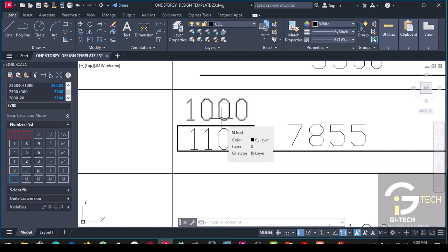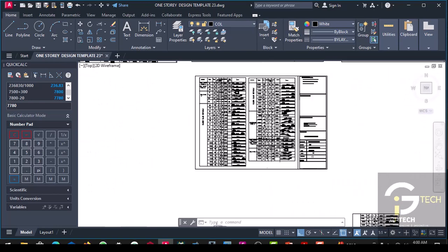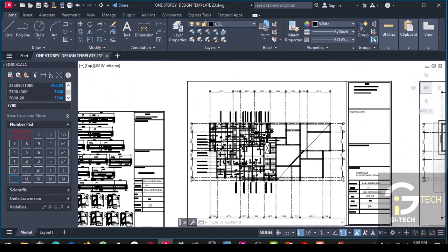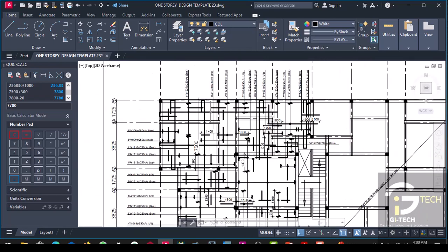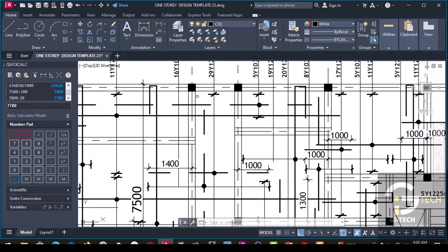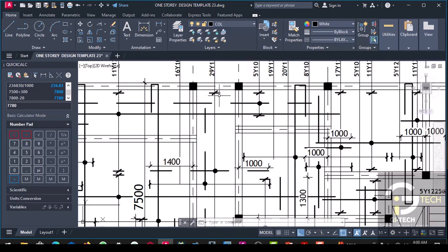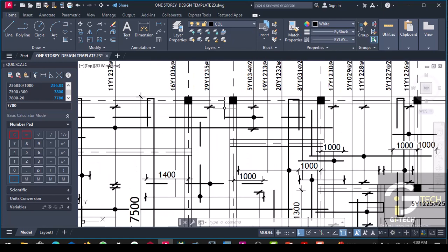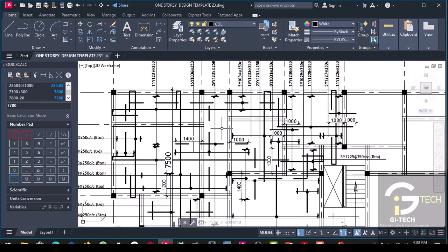Should not be less than 0.15L. Now, for practical reasons, you have to adopt something that will be uniform. So you should not just say, okay, for this span, come and calculate for this. If this one gives you, let's say, 1200, so you are going to distribute 1200 from here to here. Why this one 600? No, it doesn't make any sense.